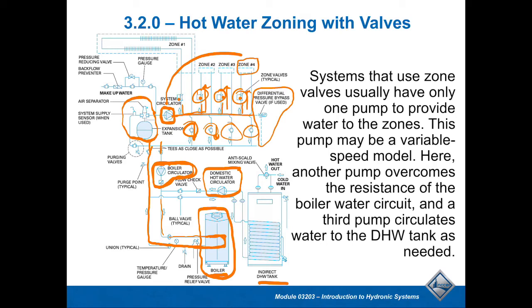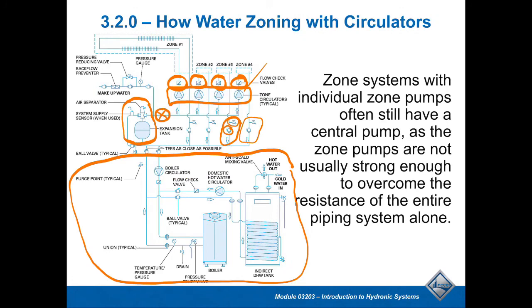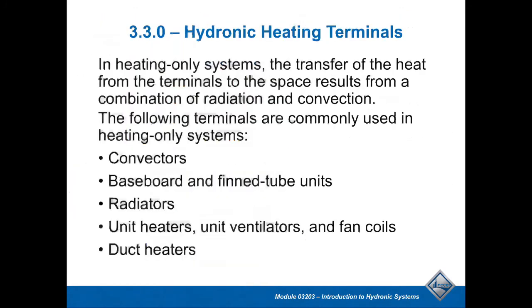You may or may not have a differential pressure valve on here. That's something that is really not needed if you are using pumps that are not excessive in head, and you can provide a sufficient flow to the remaining zones effectively. That's really where an ECM type pump has a big advantage over a conventional high head pump. There again, your pump selection really has to be spot on for these things to work right. So let's take a look at some of the terminal units.